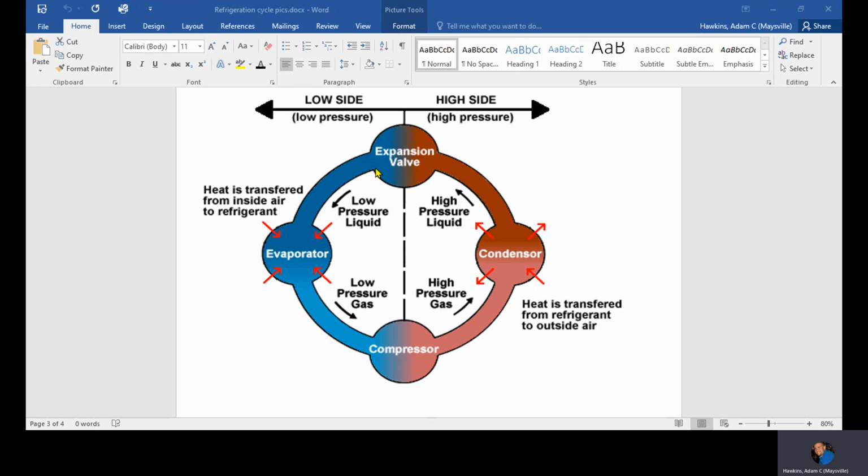It's a liquid vapor mix. So think about that spray in that bottle. That's what that expansion valve, or metering device, does. It restricts it to the point that it starts to break down. As a result, not only does it start to break down, but it also reduces its pressure. So if you can imagine, you've got all this liquid pressure coming to that piston or that TXV, and it's meeting a roadblock.